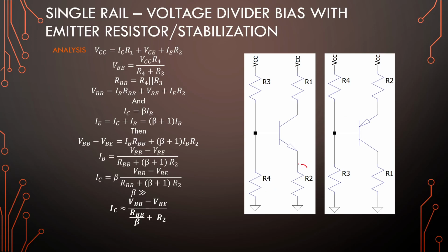Okay, so the proper way is to add an additional emitter resistor into the mix, for both NPN and PNP. Okay, so we can use the same Thevenin equivalence when figuring out VBB. And then when you're calculating or doing the loop down here, you will just have an extra term with the emitter current, and again you have the same result in the loop over VCC and the collector. So we are having feedback again, and feedback means that we have some form of stabilization happening.